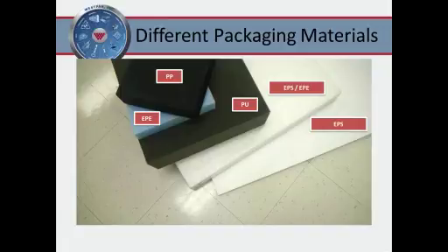On top of that, you have EPE, which is expanded polyethylene. This is very, very popular in the electronics industry, especially with an ESD coating. With EPE, you could probably deflect around 70% before hardening. And then finally, we have polypropylene, and polypropylene deflects around, I would say, 75%.